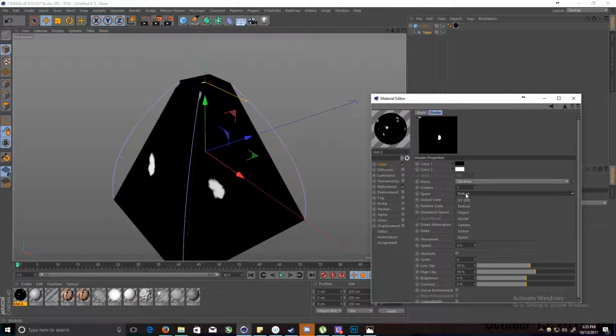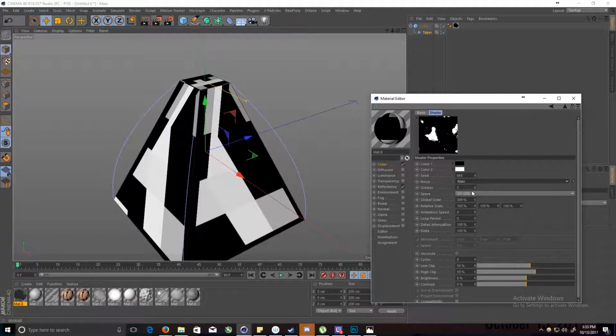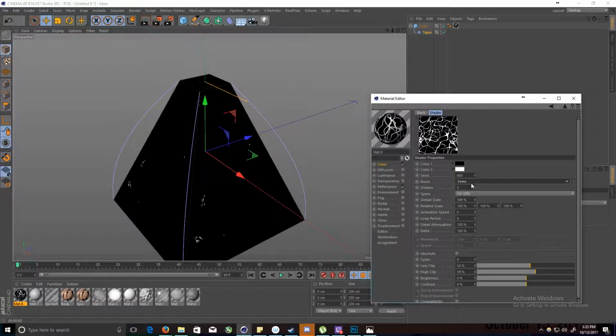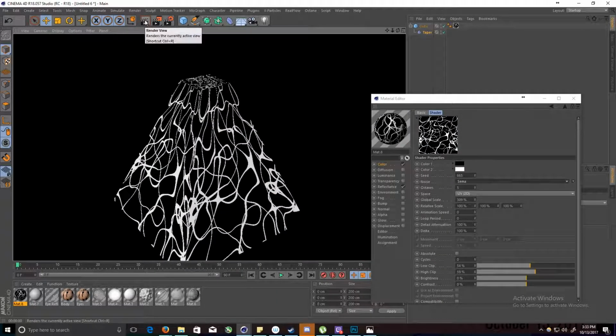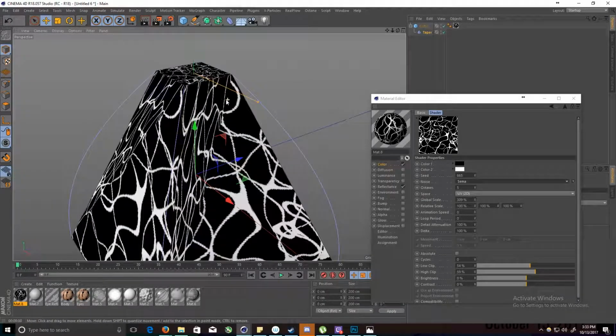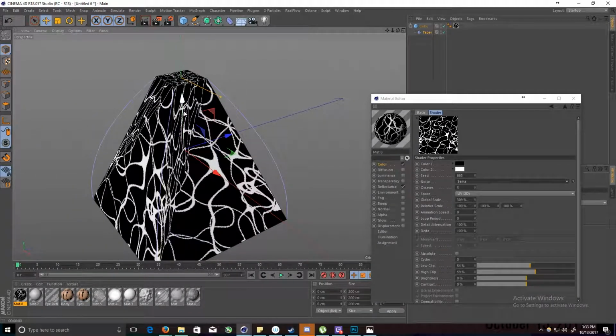If I change this to UV space, you can see how topology is starting to morph my texture. If I want it to be a uniform texture that's not stretched, I might have to do some UV mapping instead and just make sure on this polygon it's painted perfectly straight and not being deformed in any way. So, it really depends. You gotta think about it.